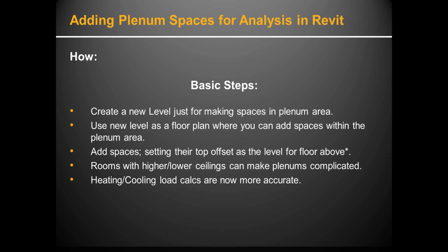So the very basic steps: create a new level at the ceiling level, where the drop ceiling is, just for making the plenum spaces. This is not something you'll use for anything else, though it could be useful depending on your other processes. We'll create a level there, and then we'll make a view from that. It's the second step here.